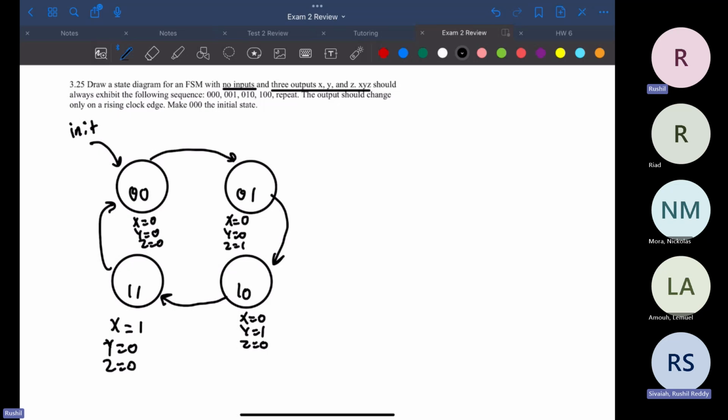Whenever you actually transition it into a circuit, you need to label what state you're in. So you're going to have a variable, let's call it S1 and S0. So this will be 00, 01 for your certain states.